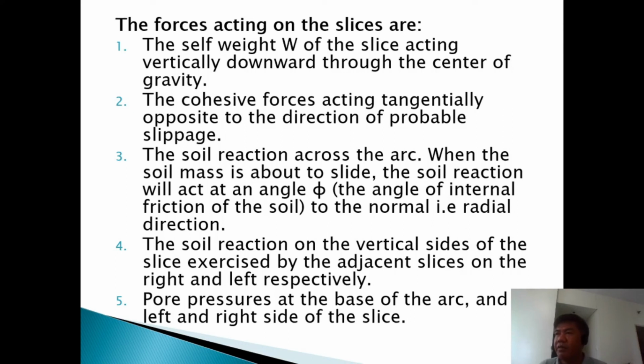So from that diagram in the previous slide, wherein you draw the slip surface, the curved surface, you are going to draw the seepage or phreatic line, which is the highest line of seepage. And you are going to determine which part is already saturated. Because of course, if it is saturated, the unit weight that you are going to use is the saturated unit weight. And above the phreatic line will be the dry unit weight.